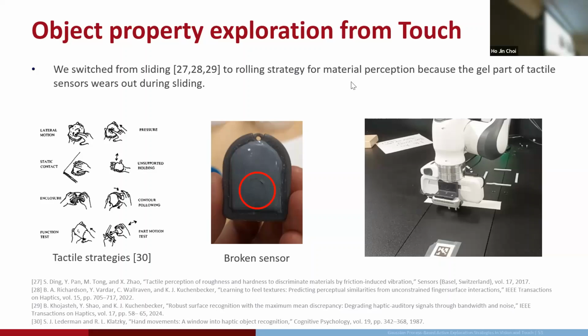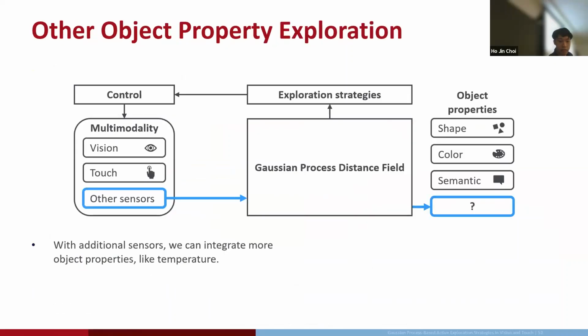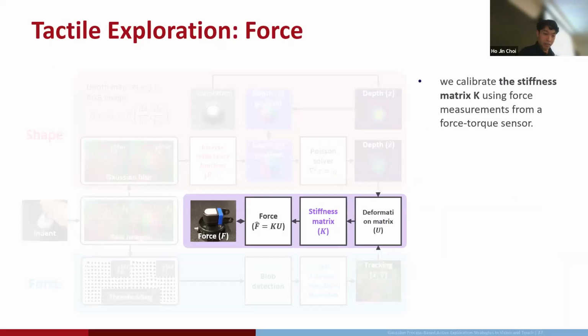Actually, we do use a force sensor. Here he used it to calibrate the tactile sensor, because the force torque sensor would be mounted on the end effector, so we might not get the best measurement of force. So what he did was calibrate the tactile sensor, but we do use a force sensor. I apologize, I missed it. Yes, there's a force sensor to calibrate the tactile sensors, and the tactile sensor is the approximation.